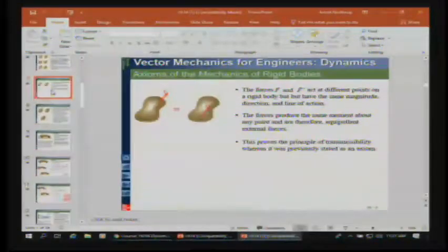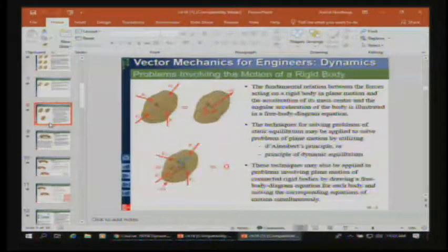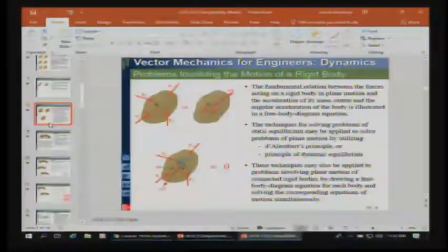All right, so if we take a look at this, we have a rigid body and we have a force acting on it here. If we move that force along its line of action, we're able to use the principle of transmissibility to say that that is the same in terms of the linear motion of that body. It may change something about the moment, which we need to take into account by taking a look at something like this, okay?